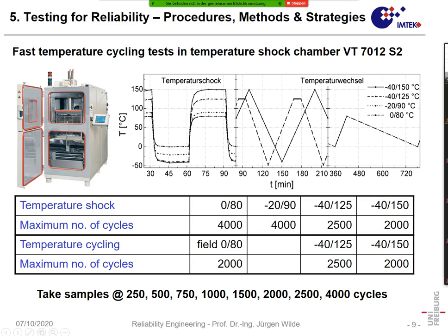So we have temperature shock, temperature cycle, and also we can have some cycle which is more or less representative of some field application. For instance, imagine a car. It is heated up quite fast, so it maybe takes 5 to 10 minutes until the engine is at the end temperature. But when we turn off the engine, it takes several hours until it is cooled down again. So for such temperature cycles we have different possibilities how to test, but temperature shock and temperature cycle are standardized tests.